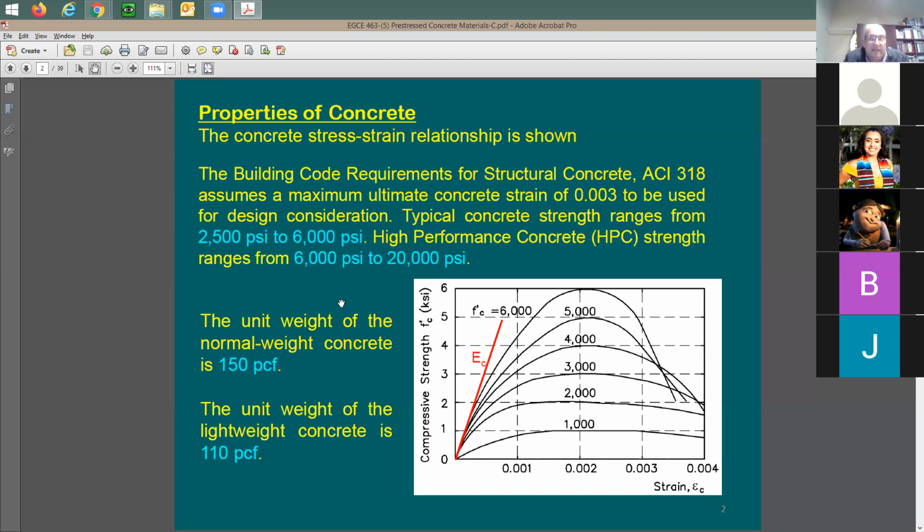When it comes to concrete slabs and concrete members, it's going to be 5,000 to 6,000. This is like the regular concrete, not the high strength. If you'd like to go to high strengths, you're going to be going maybe to 20,000 psi if you want to, maybe 12,000, 14,000. You're going to see this only in precast and pre-stressed. So you don't really need it if you have cast-in-place or conventional concrete. You don't really need to go to 12,000 psi. But maybe in precast, yes, there's a good need for it.